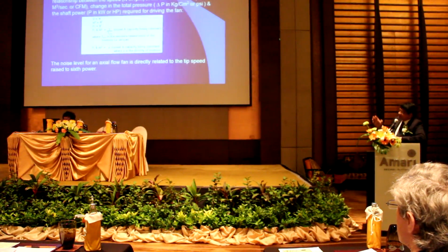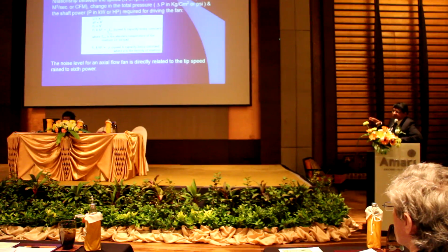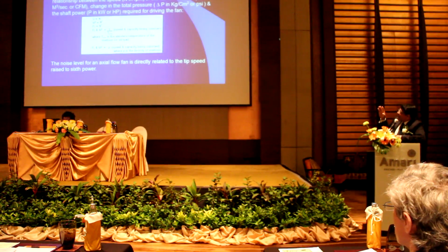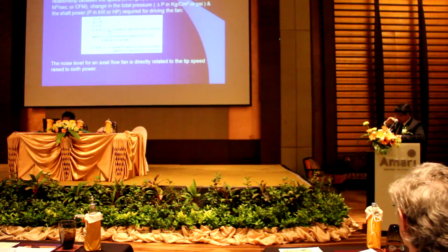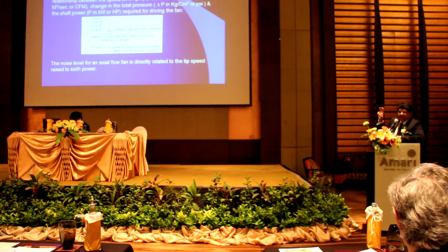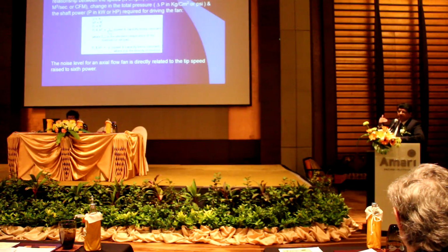And there are certain simplifying laws, although they are not very complicated, but one needs to understand these things basically because, as you can see, the power varies as the cube of the speed. So some people think, why don't we just increase the airflow by increasing the fan speed? Then obviously your motor will be a limitation.